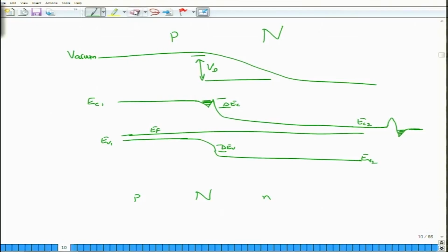Eventually the region here on the N type material would actually have the same value of EC. So, we will call this EC3. This one would simply drop, have a sudden transition and then move back to EV3. Okay. The Fermi level, of course, I did not write it correctly, but the Fermi level has to be constant. Okay. So, I should have written down the Fermi level first and then made these bends as such.